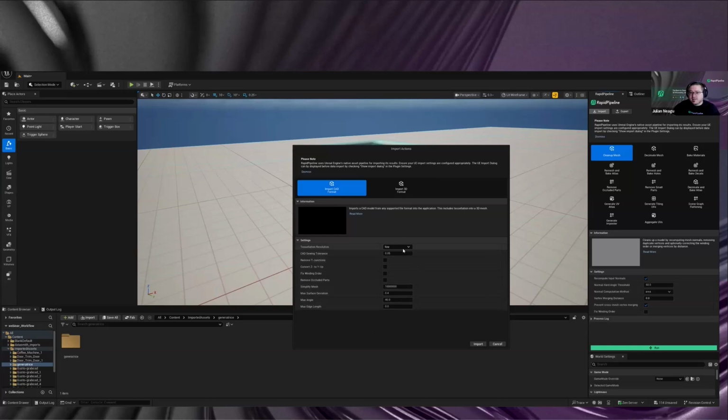So for the CAD side, you can really dive a bit deep into the tessellation algorithm and how that actually works. You can select a preset we offer right now, or you can select a custom tessellation, and then you can steer the whole tessellation process with further settings. For example, we have a value for max surface deviation, which is also explained in detail in the documentation. Then the max angle of the tessellation when trying to fit and project the triangles on top of the parametric surfaces, the freeform surfaces, and then also max edge length, which can help if you have very large flat surfaces.